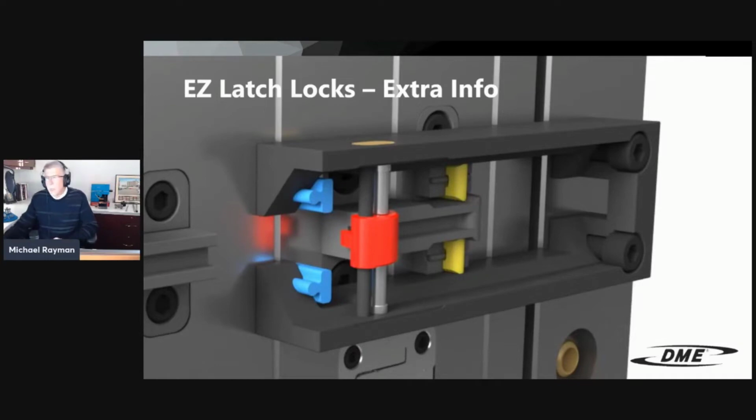So with the latch locks, we offer 3 different series for different sizes of molds. We've got 3 body sizes for each of the series and 5 latch bars for each of the lengths. The bodies themselves are made out of 5140. The latch bars are H13, 46 to 48 Rockwell, along with the returner. Everything is nitrided and black oxide coated for smooth action.